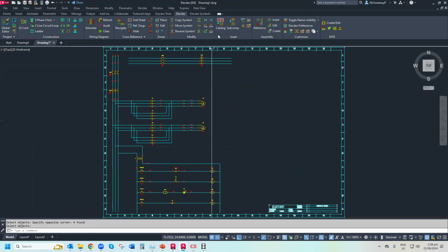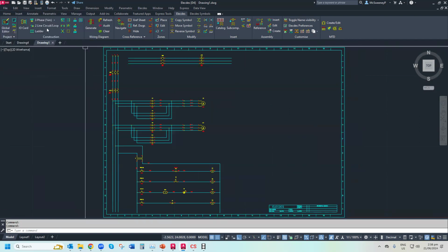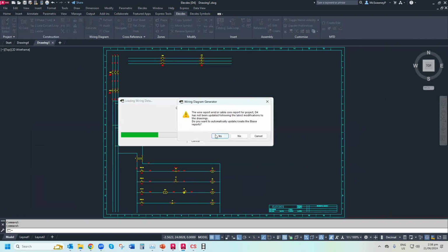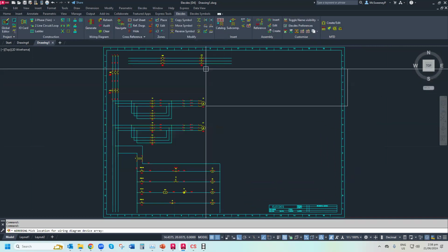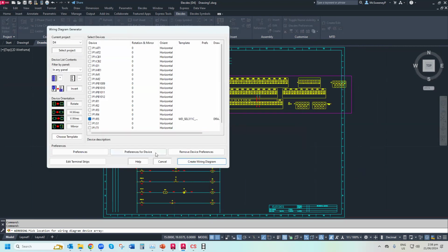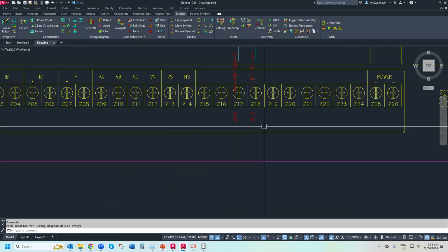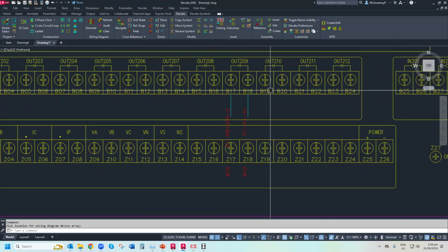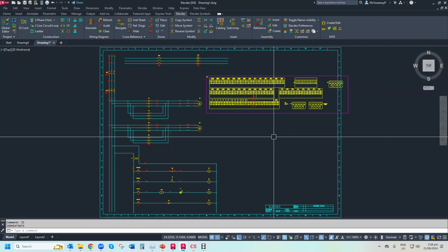I get rid of them because the next thing I'm going to do is go File, Save, and generate wiring diagrams. And now if I have a look, there's that relay that I just put the contact in for. Takes up a bit of space. So again, if I cancel that, there's further proof. If I have a look in, there's my wire 18 and wire 19 going into B17 and coming out of B18. So there's proof that we can automatically produce wiring diagrams, and that's a bit of a wow moment for a lot of people as well.